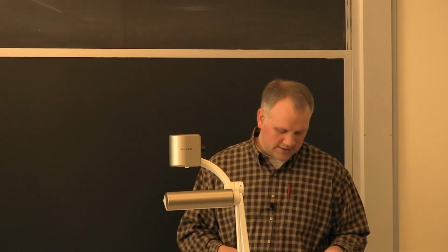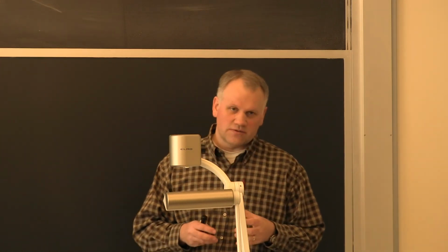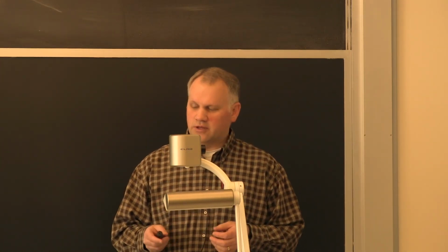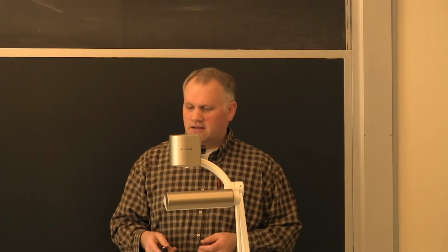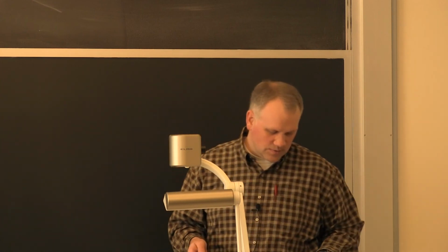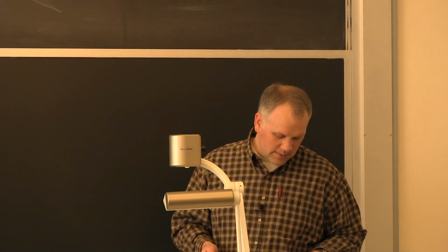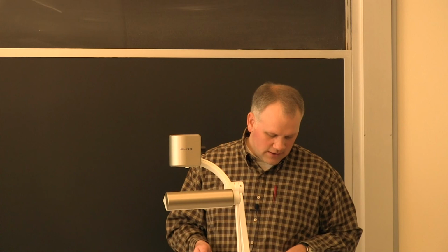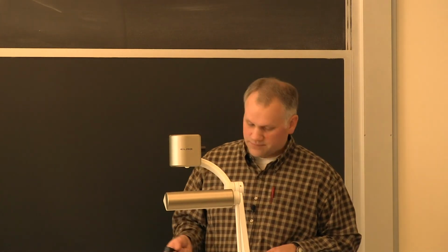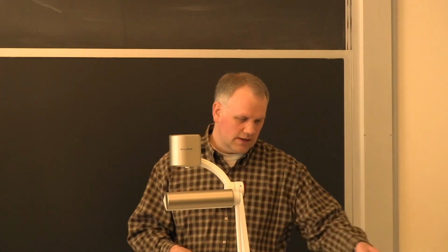And submerged arc is the last one I've got up there. Submerged arc actually has specification for the flux and the electrode. I don't know if you're familiar with submerged arc welding, but you're actually welding through a big blanket of flux. And so they specify the flux as well. So that's why you've got both F and E. You've got a strength and chemistry requirement on the flux, and then you've got chemistry and manganese contents on the electrodes as well. And these are all things that are spelled out in various codes and handbooks and stuff as well.